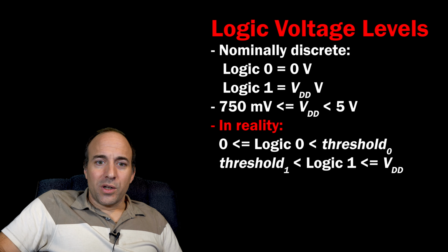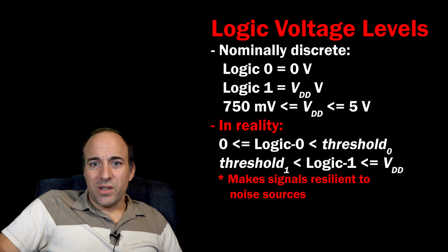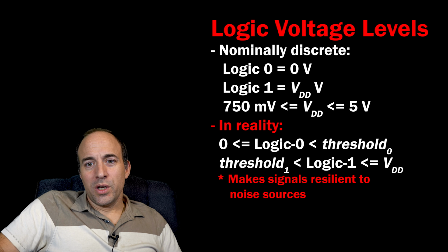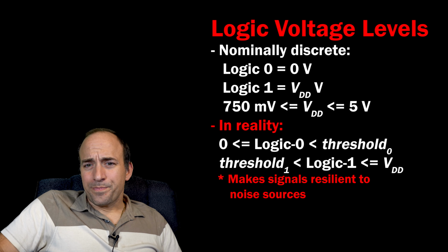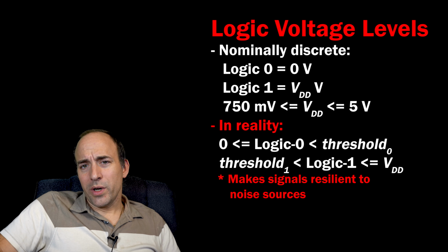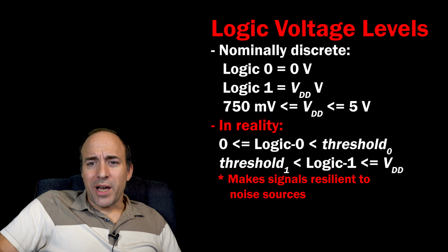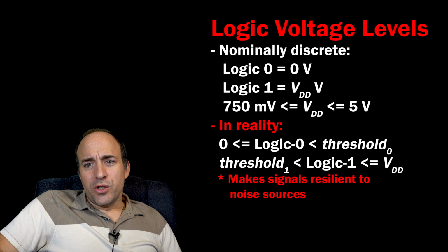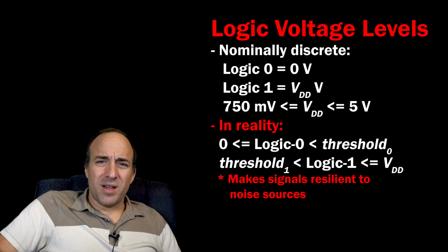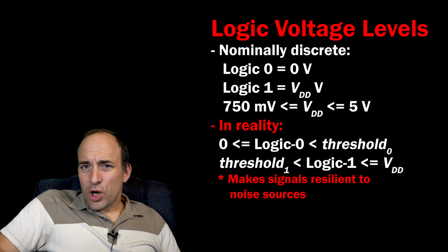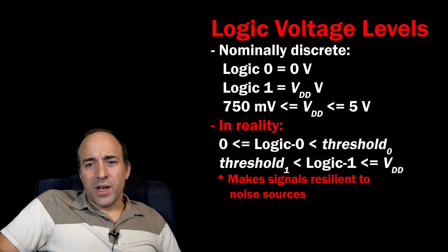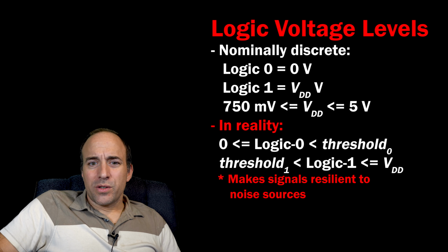Noise sources include wire resistance, which causes the voltage to drop the further it passes along a wire; power supply noise, in which the supply voltage changes due to the logic gate switching activity causing temporary spikes on the supply voltage; and crosstalk, or capacitive coupling between neighboring wires.